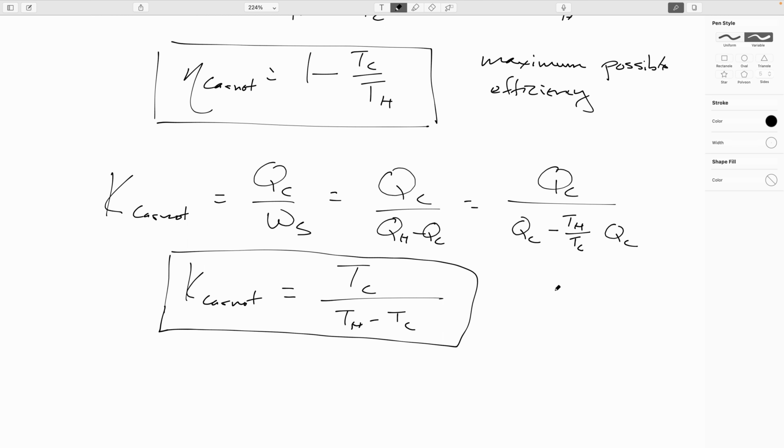This is better than running a furnace. Running a furnace, the best you can do is hope to get all the chemical energy that you liberated burning the natural gas or whatever. You hope to get all of it out, 100% efficiency, so a coefficient of performance of 1. You're never going to get that in practice. You're always going to have at least a little bit of loss, and at this point it's been engineered to about 98%, so that's as good as you can hope for.